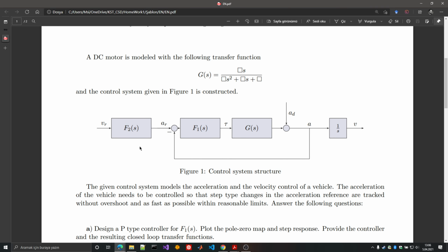Now, this is provided here. We have an open loop here, and we have a closed loop here. I didn't bother to put a feedback structure in the outer loop. I didn't want to provide you a second feedback because it would be too much work, and it's too early for that. We have a feedback loop for the acceleration. So if you provide an acceleration, you are measuring the acceleration and feeding back the data, and you're constructing this loop. And then you will have a closed loop.